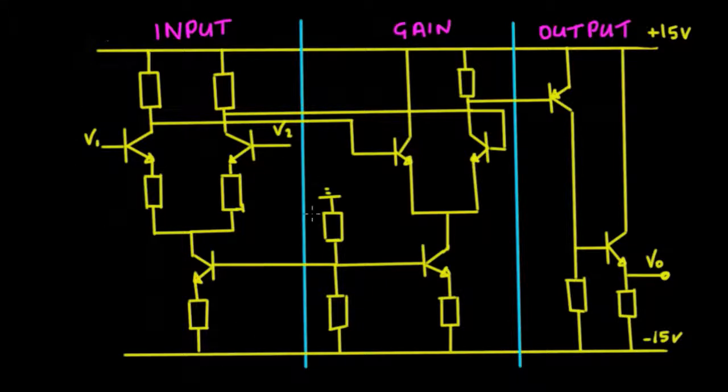So don't worry if you've not seen this before, we're not going to be using this and we're not going to be designing it at this level. It's just to give you an indication of what an Opamp is. So that input stage passes on to a gain stage, which again is another differential amplifier, and it amplifies, this gives us most of the gain in the amplifier, and then it passes on to an output stage there, which allows us to drive lots of different loads.